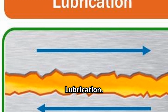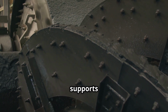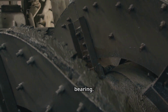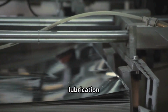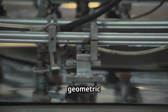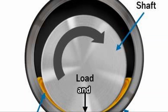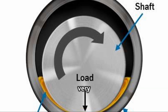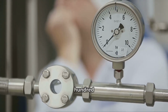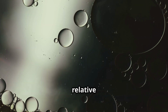Hydrodynamic lubrication. This lubrication regime occurs between sliding surfaces when a full film of oil supports and creates a working clearance, for example, between a rotating shaft and journal bearing. In order for hydrodynamic lubrication to be successfully and completely applied, there must be a high degree of geometric conformity between the machine components, such as the curve of the shaft and the curve of the shell in a journal bearing being very similar, and a resulting low contact pressure, 100 to 300 psi in industrial journal bearings, between the surfaces in relative motion.